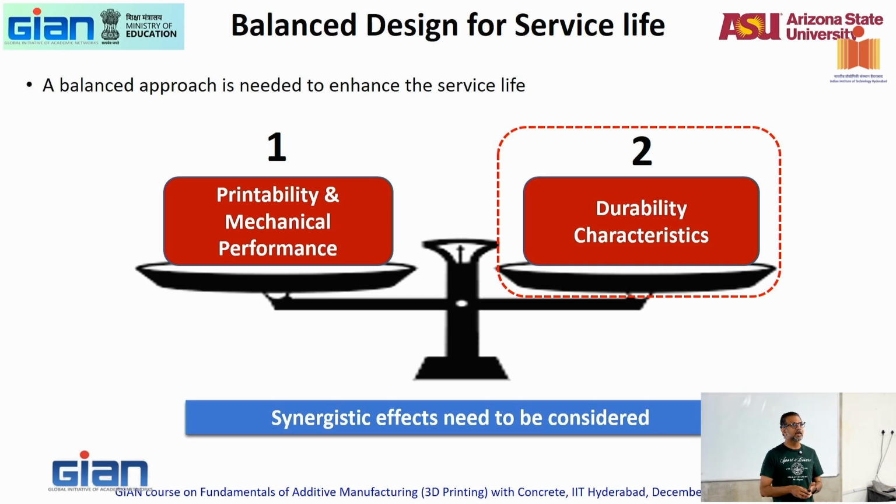If you watched carefully yesterday, did you see them placing rebar on the lintels when they were printing it? So they actually put rebar on the lintels because they were printing the lintels too. The tensile stress are going to be very, very low. So even if the bond between the steel and concrete is not very good, that's not a big problem there. It's going to be a very small structure. But when you get larger structures, some of those issues will become critical. Generally, we don't have much rebar in 3D printed concrete, so we don't really know about corrosion performance. We don't have that much data.